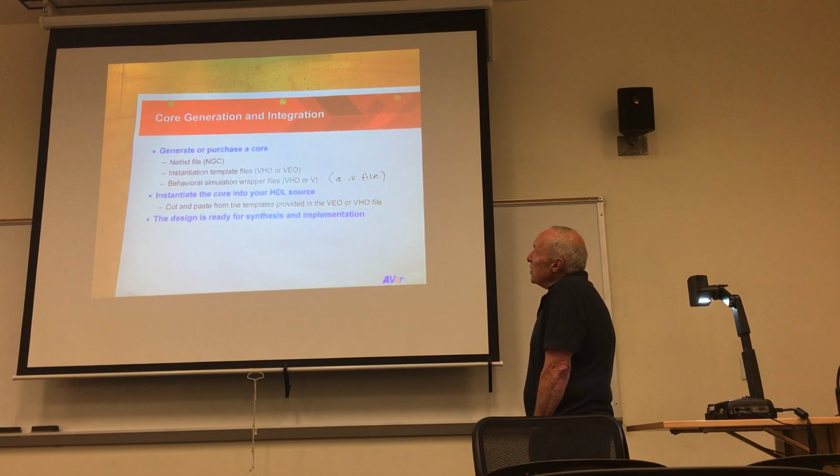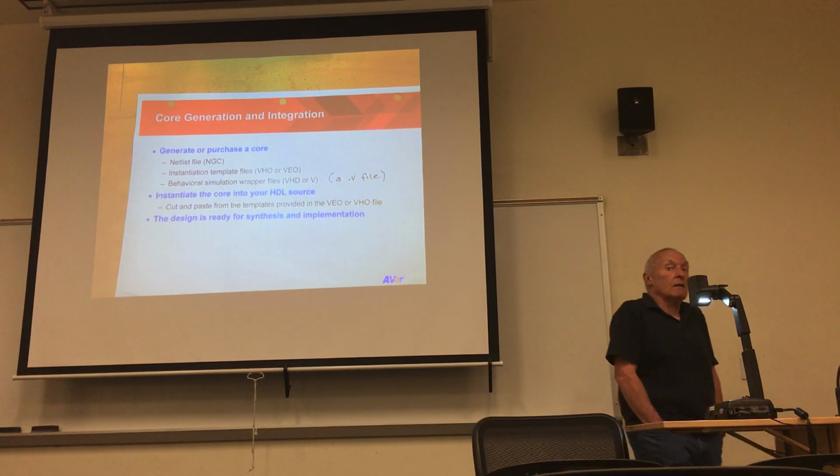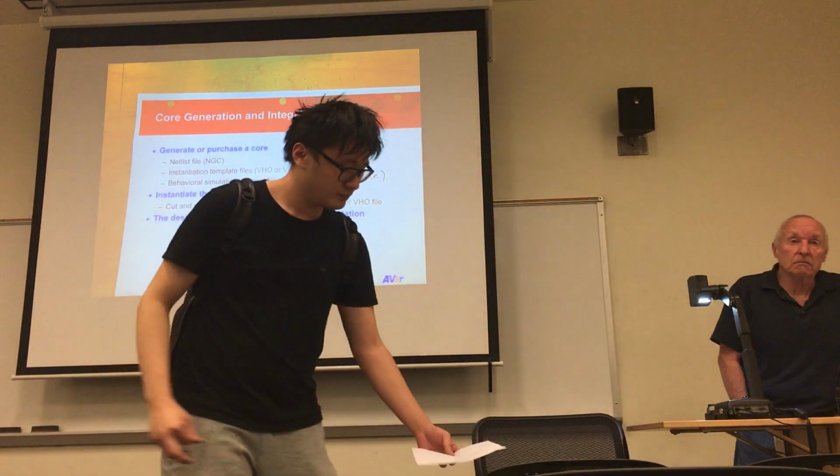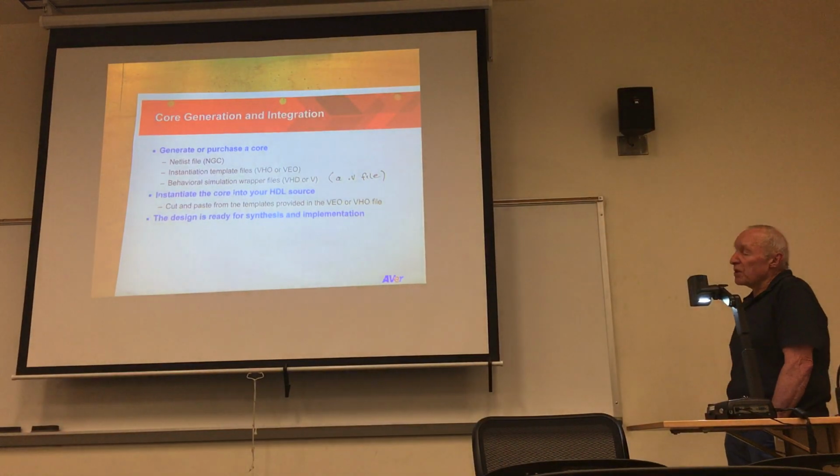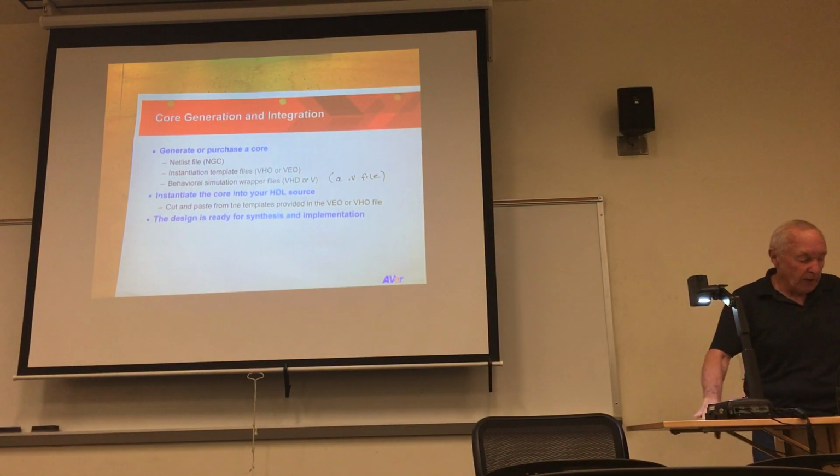And then we have this wrapper file that's used for simulation. It's a .v file, and you do not synthesize it. It's only used to support simulation. Okay.